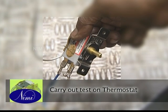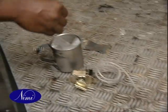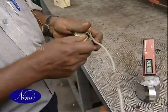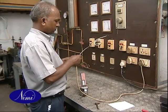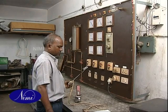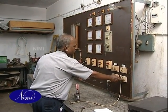Carry out test on thermostat. Crush ice cubes and place them in an insulated container. Mix some salt with the crushed ice cubes. Insert a thermometer inside the container. Take a thermostat and check electrical contact points. If necessary, clean the contact points with fine sandpaper. Connect two wire leads to the thermostat. Connect a bulb in series with the thermostat. Connect the other end of the wire leads to a 2-pin plug and plug it in the test board and switch on.